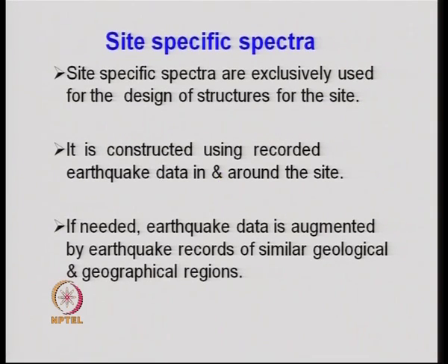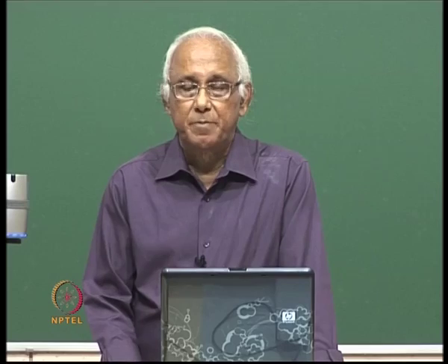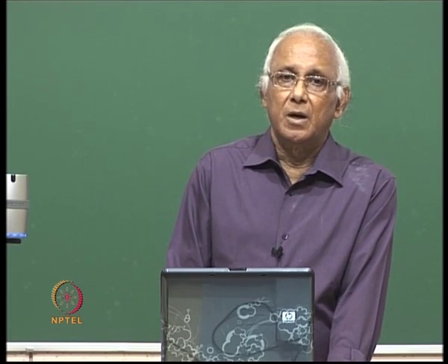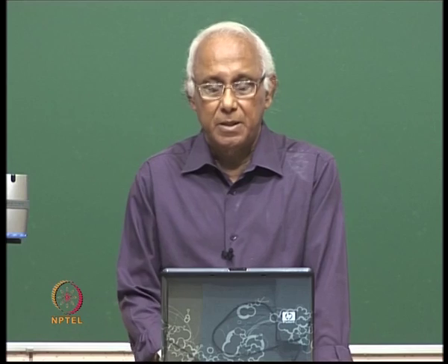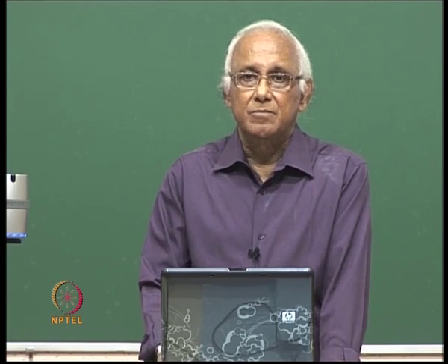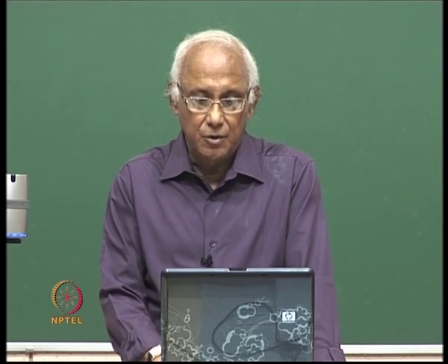Next we come to the site specific spectra. The site specific spectra is called a site dependent response spectrum, and they are used for designing specialty structures for a particular place, and that particular place may have certain characteristics in terms of geology and geography.